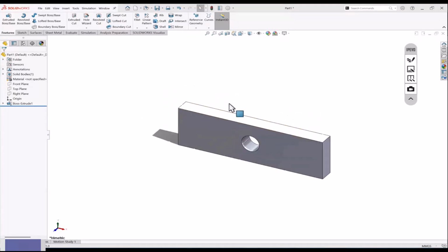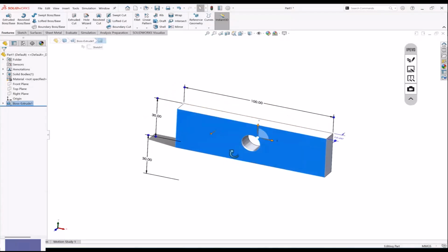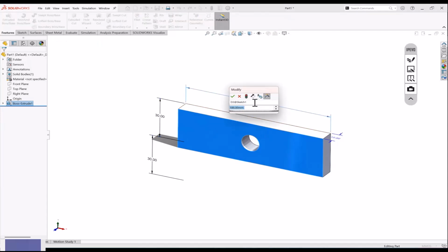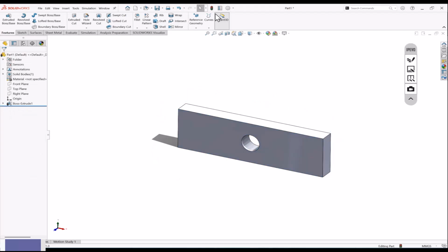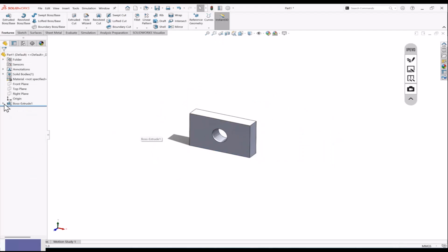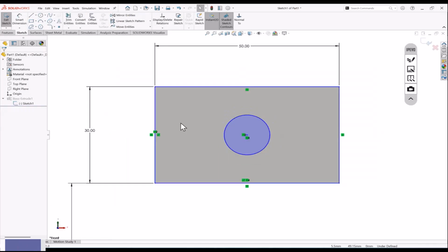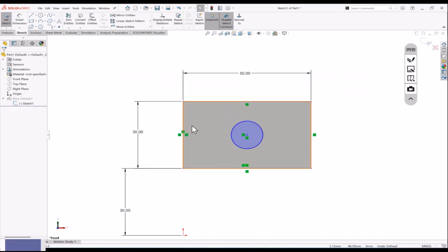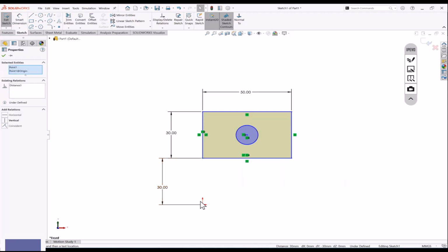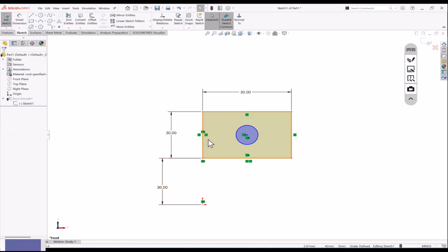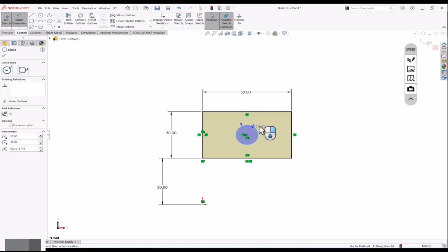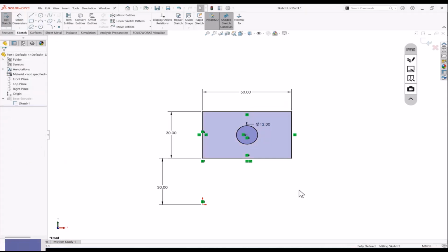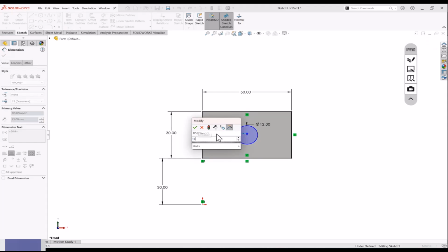Okay, so we can see. Like this we update. Whatever size changes we make in the part, we update, and we have to rebuild if it does not update. Now, if I had not done this with proper relations, let me break the relations. Okay. So let's maintain the other relations, which were removed, and the size. Now, if I do not use this relation and put the dimension instead of that, let's see practically what will happen.